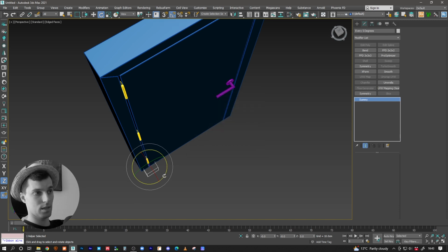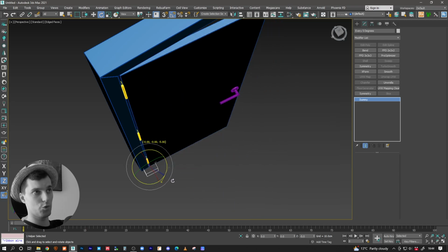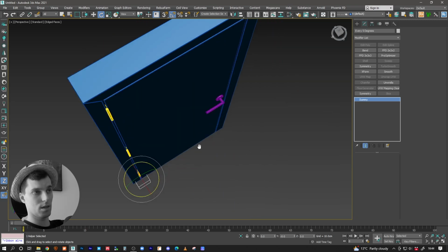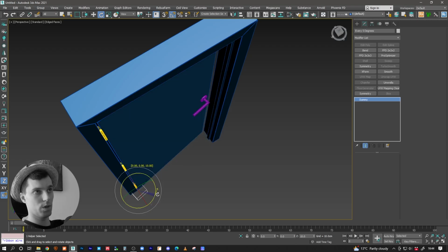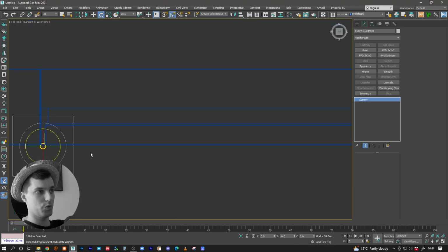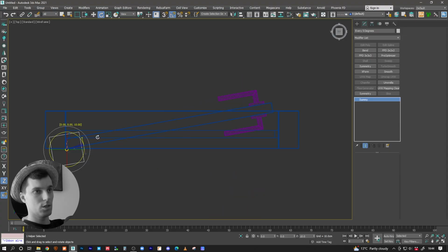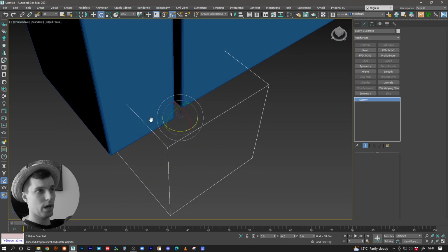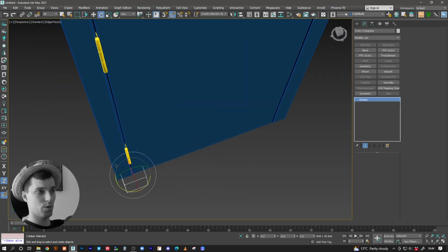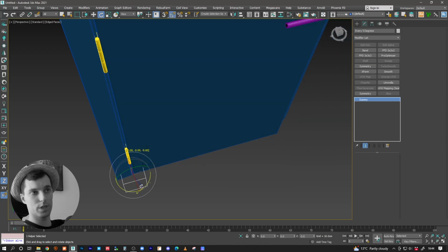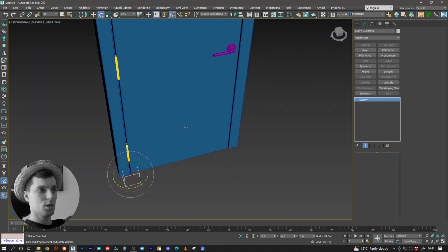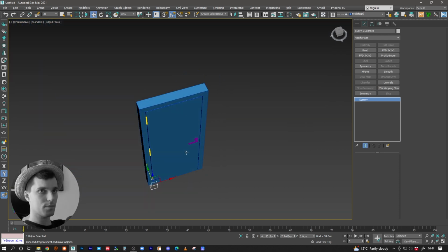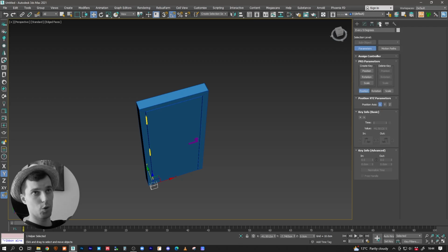If I activate this and bam bam bam bam bam, I will always go to that nice middle location, right? If I go to the top view, it's always gonna be straight, as you can see here, right? So this can work, but you have to know exactly how many increments, and don't rotate without it, because it's going to be hard for you to get the same center location. So how to make this more rigged is basically go here into motion,